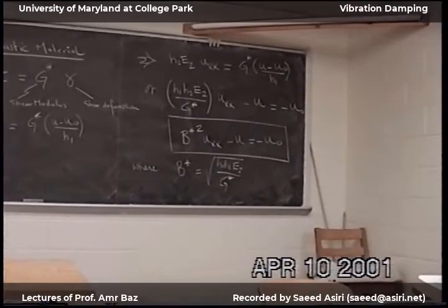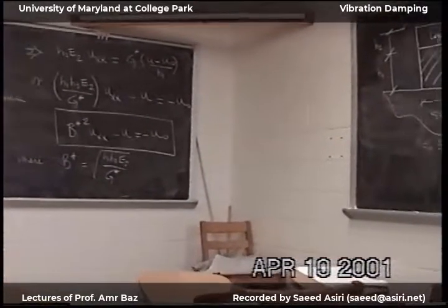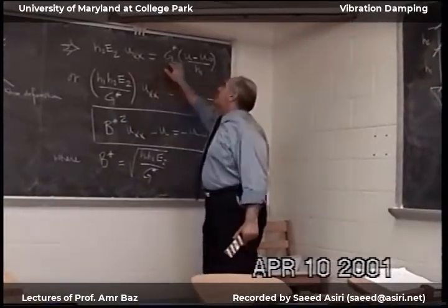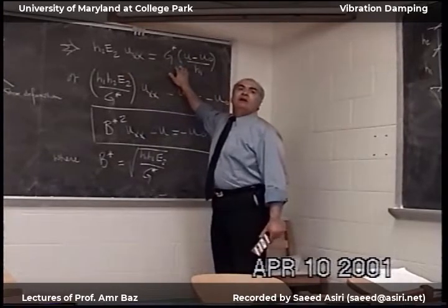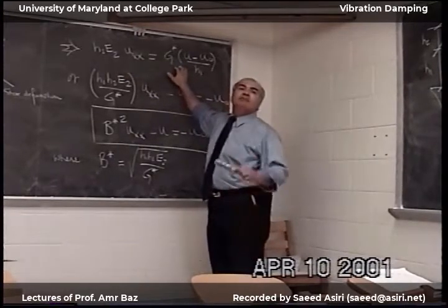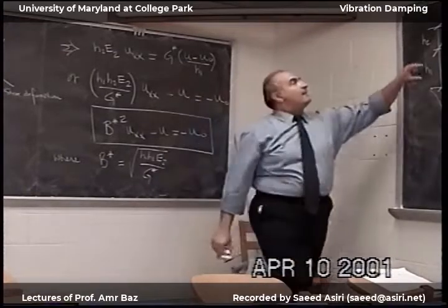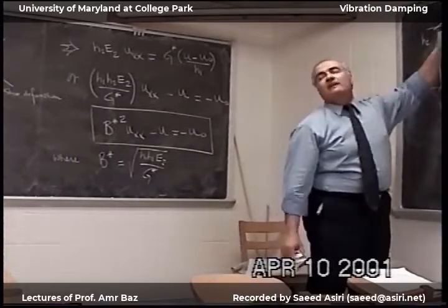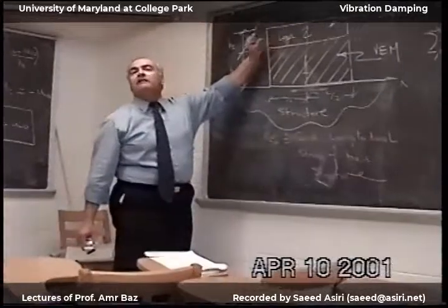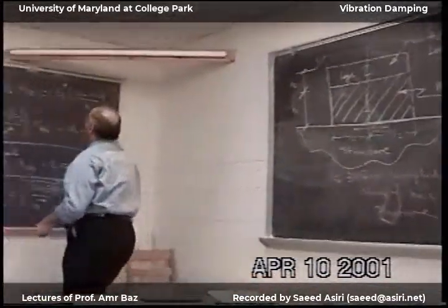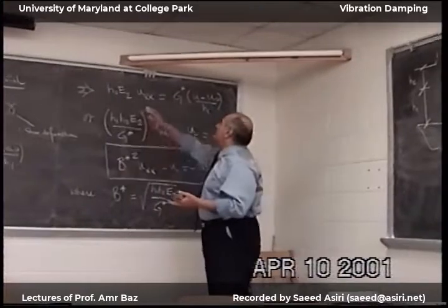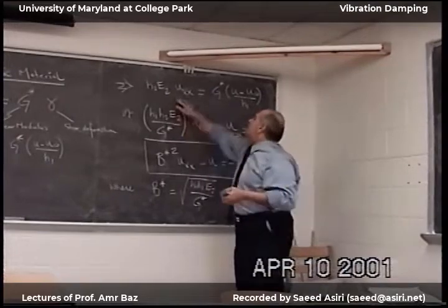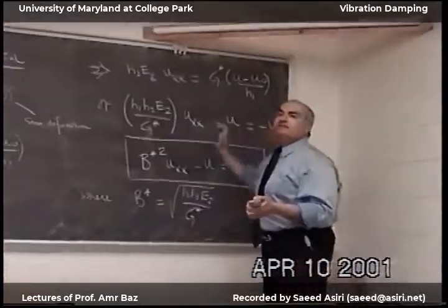The thing that I wrote here is for quasi-static equilibrium, because I looked at the stress and we counterbalance it by the shear of the viscoelastic material. We did not put the inertia of the viscoelastic material, of the constraining layer. If this material is relatively thin, the inertia will be negligible. Okay? So that's the approximation that we have. We put in equilibrium static forces, whatever stretch we put in the constraining layer, we counterbalance it by the resistance of the viscoelastic material.